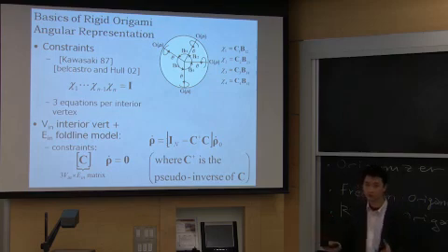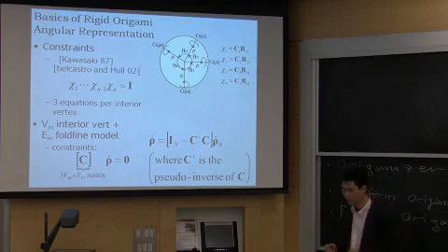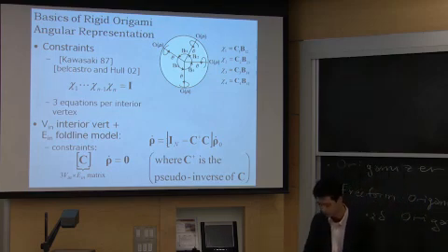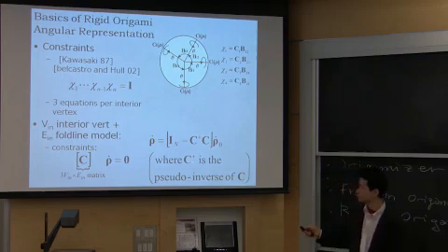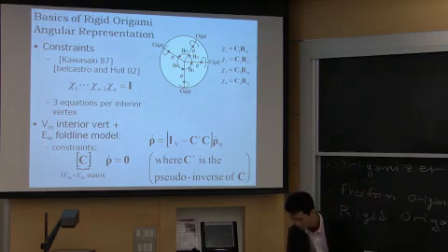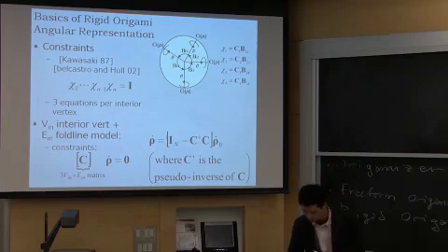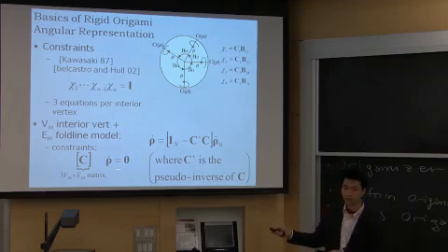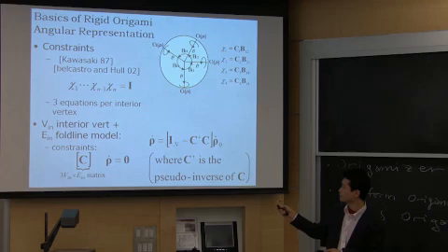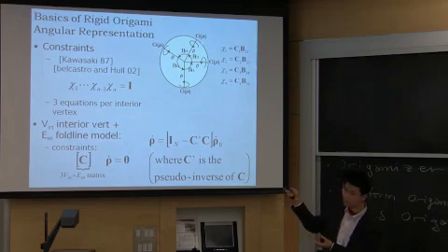That gives an underdetermined system, so that you can simulate folding using a generalized inverse, so that you can search within the solution space by giving a kind of force asserted to each of the edges, and then this results in a deformation that is valid.